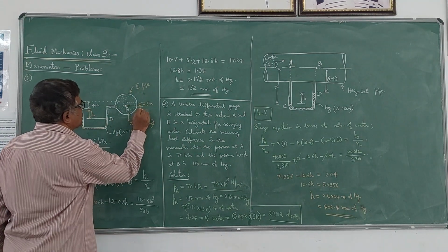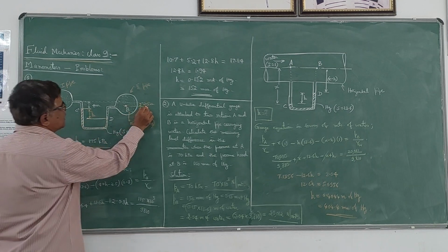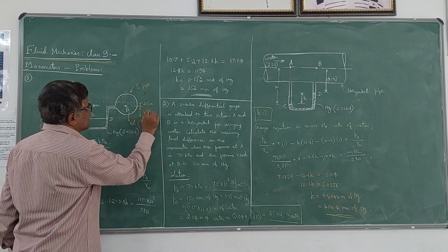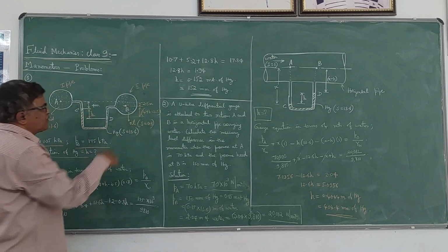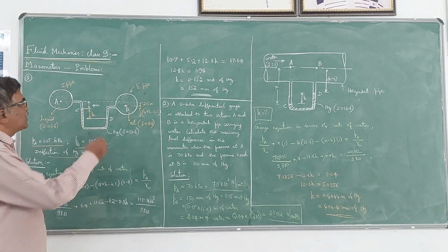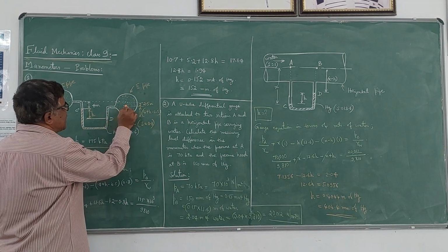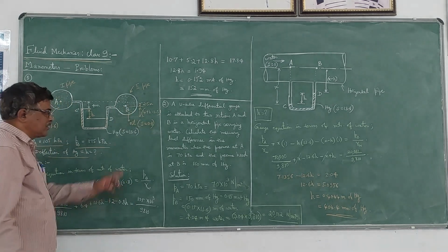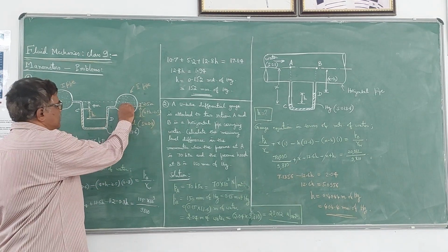According to this sketch, it is 4 plus h minus 2.5. So 4 plus h minus 2.5 is the elevation difference between the points D and B, which we have to multiply by the specific gravity of the liquid between D and B, which is 0.8 here.